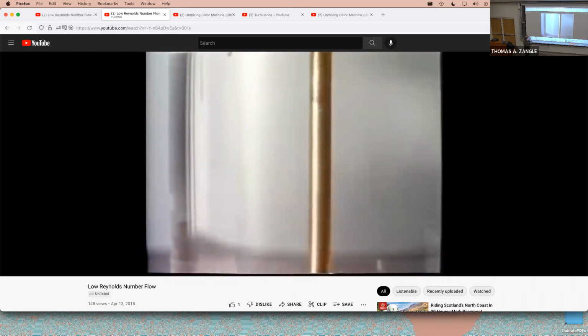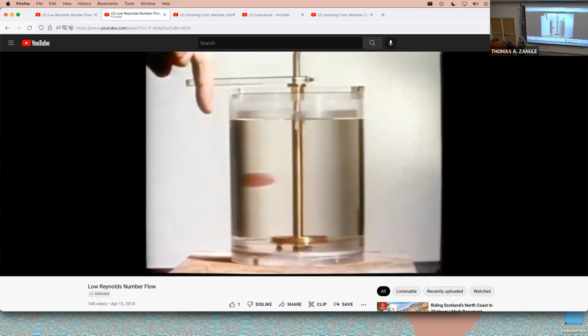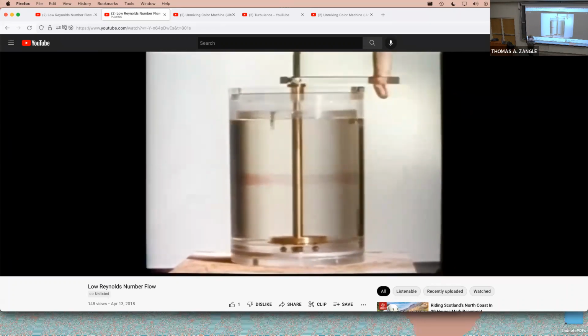The annulus between them is filled with glycerine. Into this space, I introduce some dye, which stays put owing to the high viscosity of the glycerine. Note its position before I start turning it. I now turn it 4 times, pushing the handle clockwise. The dye seems to mix as a drop of milk mixes when it is stirred into a cup of tea.